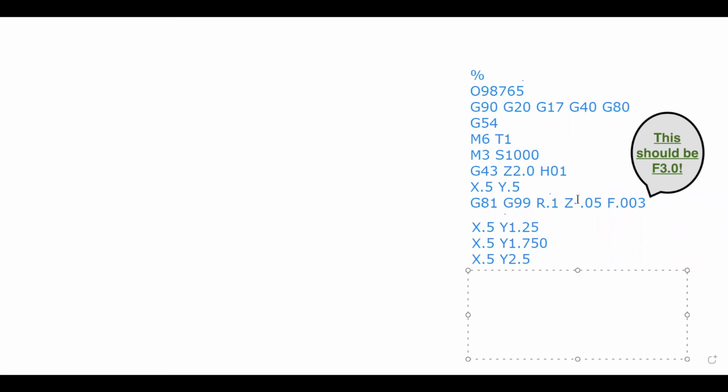So once all of our points are finished being entered into our program, our next line is going to be to cancel the canned cycle, which, if you remember up here, is G80.